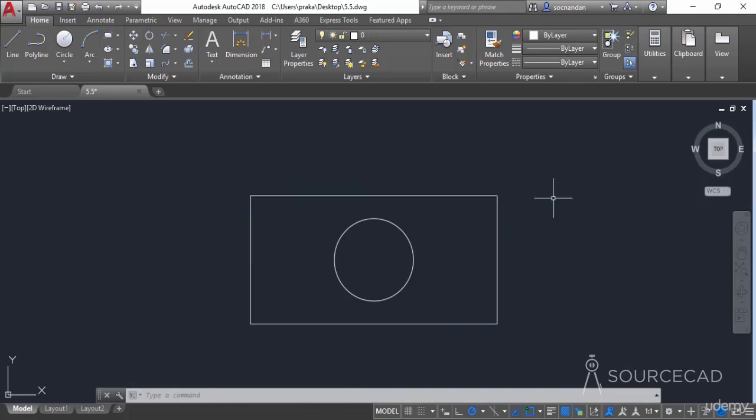Now using grips, you can also modify your geometry in many different ways. For example, on the modify panel, we have multiple tools like scale, stretch, move, and copy or rotate, and we have used these tools from the modify panel. But instead of selecting them from the modify panel and using them from here, you can directly use the grips. Now in this case, we have this complete geometry.